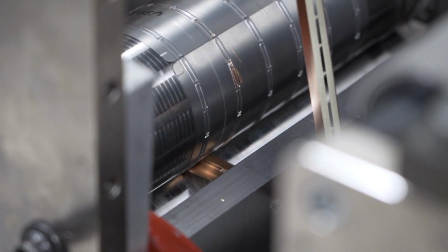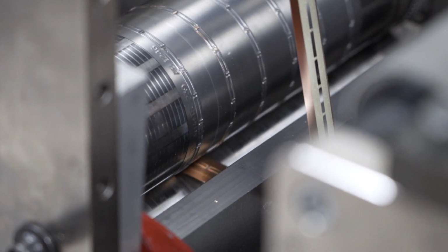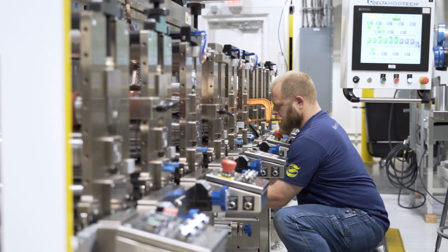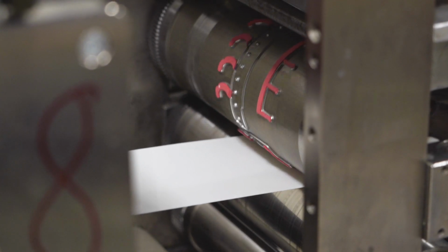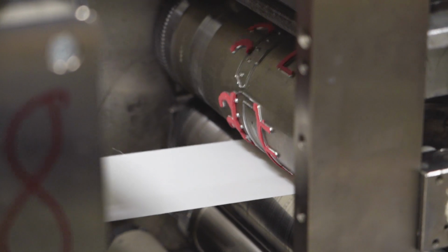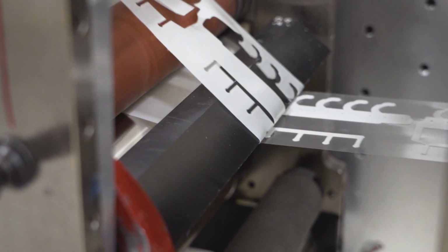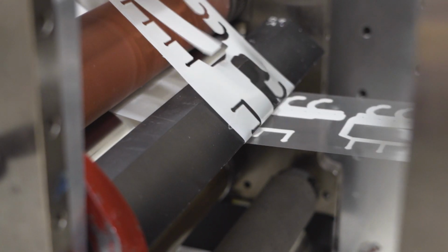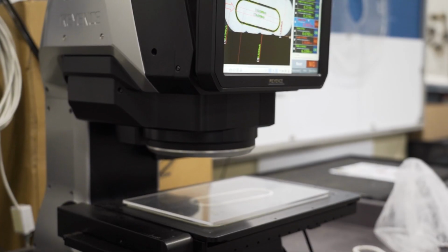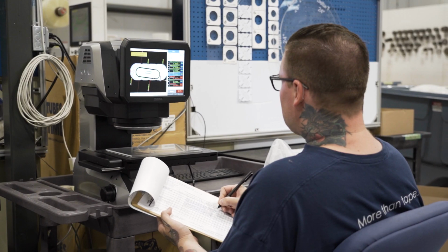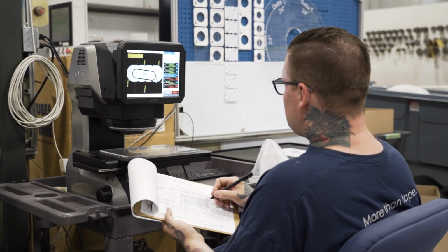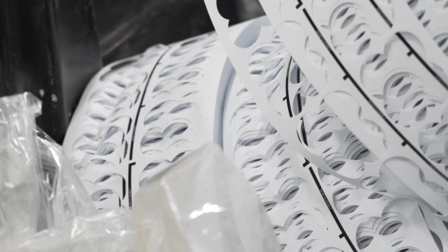Challenging part designs with multiple layers or tight tolerances can result in more waste. To make a die cut, we have to use material that is wider than what we are cutting. More materials and more complex design exacerbate the use of materials. Additionally, setup and testing needs to occur before we start running your product, which requires additional wasted material. So refining your design and seeking converter input can reduce your waste.